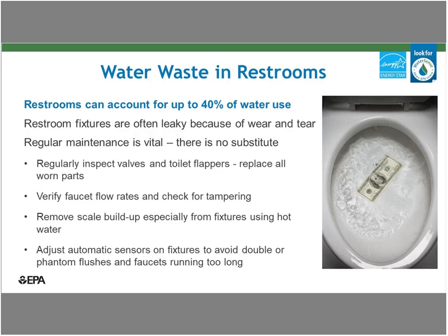Unfortunately, sometimes users will take the aerators off a faucet because they think it's not working right, and that can really impact water usage significantly. And then for the fixtures that use hot water, you want to make sure that you remove any scale buildup, because it does really affect the performance of the fixture.